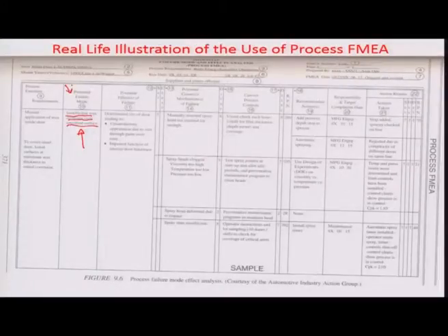failure mode happens because of insufficient wax coverage over the specified surface, which relates to a process function requirement, which is about the main functional requirement of the wax is to sort of manually apply inside the door so that you can cover the inner door lower surfaces at minimum wax thickness, and corrosion can thus be retarded within such assemblies, door assemblies. So the potential effects of these failures may be many, including it may lead to deteriorated life of the door or the door parts.